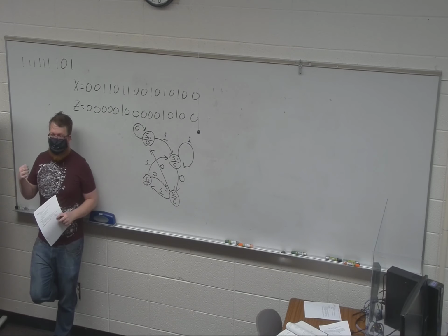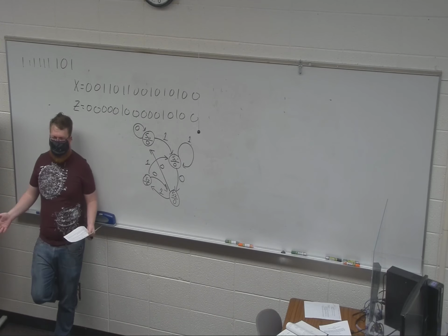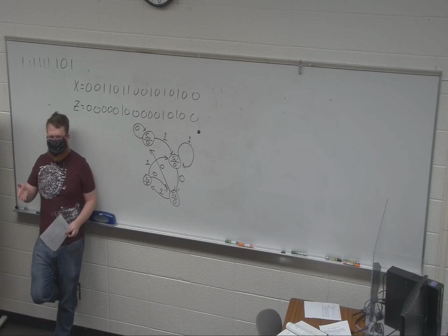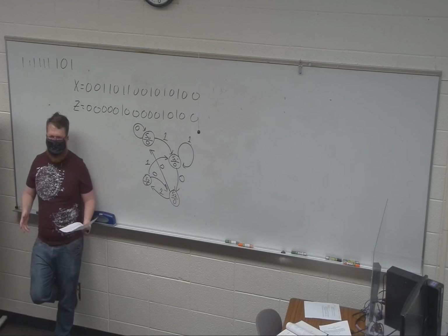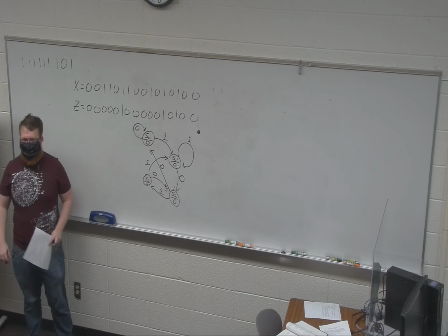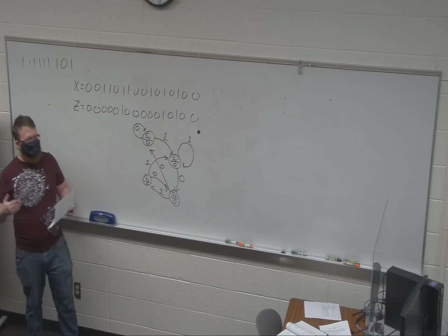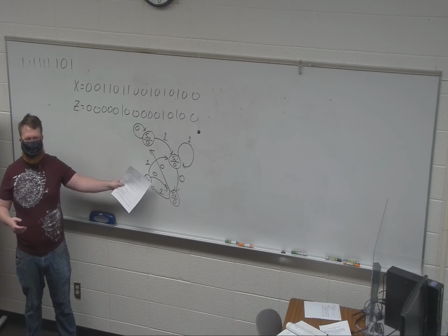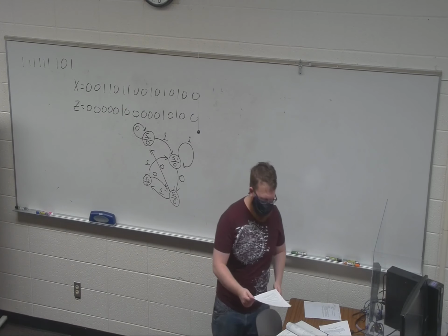The K-maps used to be way more important than they are now. They're still very useful, but when you had 100 logic devices on a chip, reducing something from 16 to 10 gates or something would be hugely important. Now we have like 10 million devices. So if you have a couple of extra states, it's probably not going to matter unless you're in really high-speed systems. So it's still useful to know to do the right states, and you're less likely to cause some weird errors if you don't have extra states.